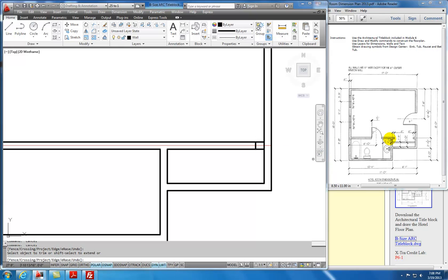And then we'll offset that line, actually on this side, 6 inches. So we'll say offset 6, this line to this side. And then we'll extend that line out. So I hit escape there, grab this grip, bring that up, grab this grip, bring this up, hit escape. Again, we'll trim, enter, and parts to be removed. And so that's our basic closet opening.